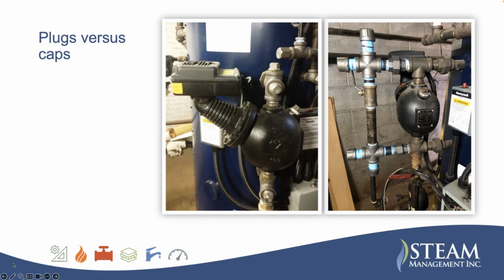These have to be opened up every year. This is what senses the water level inside your boiler. This has to be removed. All these caps have to be removed, and this has to be cleaned to make sure it's not plugged so the boiler doesn't dry fire.